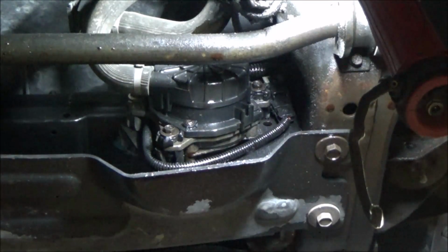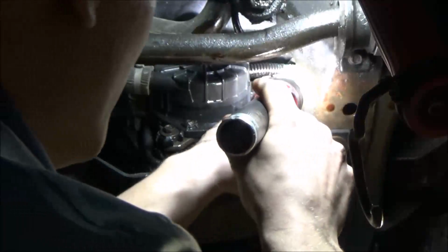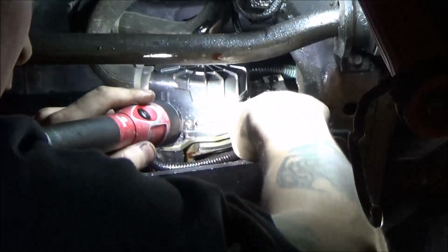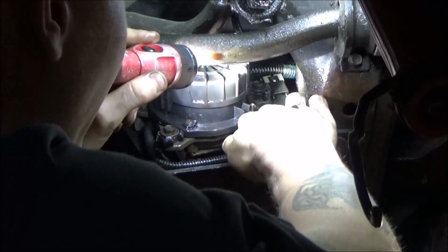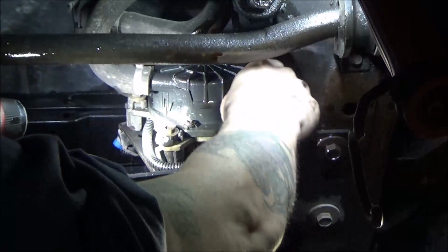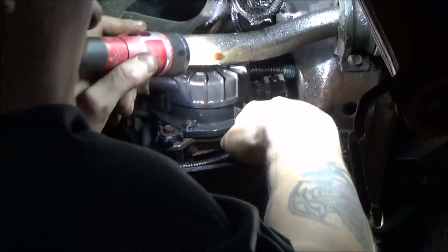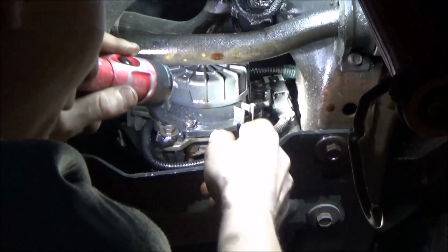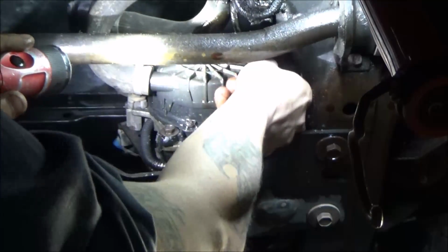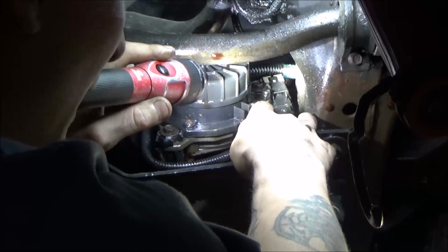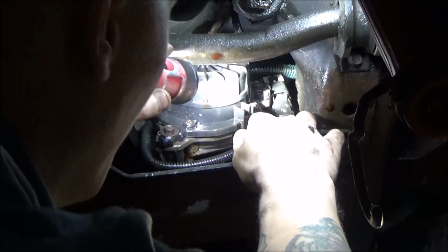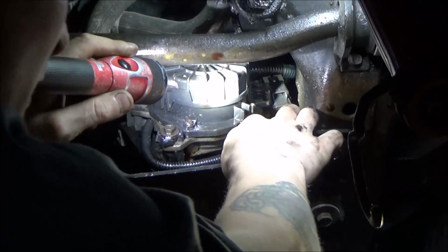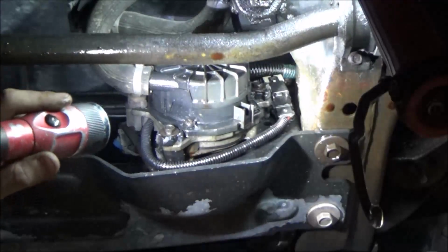So we're going to be executing our tests here, and I'm just taking a look at it to see what sort of wire colors we got. And all of this is completely covered in what appears to be transmission fluid. I can see a red and a black. You know, the logical part of me says that this red wire is likely going to be the power feed to this pump, this motor, excuse me, and the black one is going to be the ground.